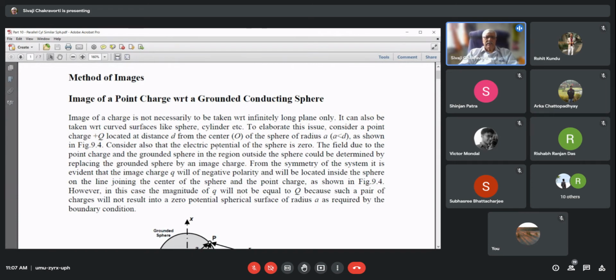One of the spheres is typically at high voltage, the other one is earth. This is the typical sphere gap arrangement used extensively all over the world in high voltage engineering. It is used for measurement of voltage, for calibration of equipment, and so on. And this is also used as a very fast acting switch.